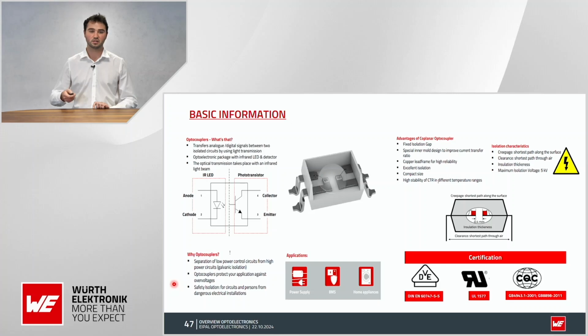So you need this basically everywhere, in different power supplies and home appliances. Everywhere you have different circuits which operate on different noise levels. For example, the LED would be on the microcontroller side, and the phototransistor on the other side, which is like a more dirty circuit, basically.